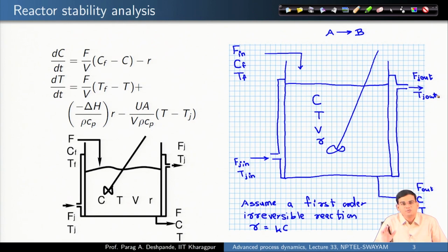Similarly, to maintain a constant temperature, to take out the heat of reaction for the case of exothermic reaction, or to supply equivalently the heat to the system for an endothermic reaction, you generally will not have a jacketed system, you will have a coiled system, but in either case to have the energy exchange for a diabatic operation, you have the flow rate of the fluid in the jacket given as F j in and outlet flow rate as F j out, j stands for jacket.